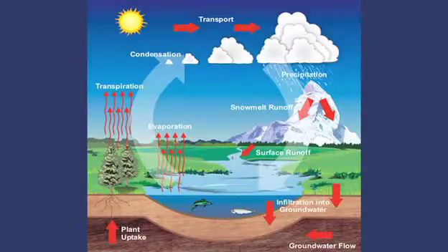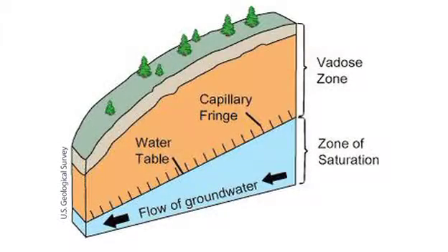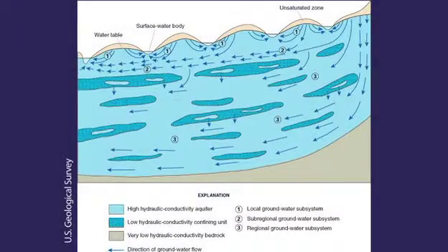Infiltration is the process by which precipitation is abstracted by seeping into the soil below the land surface. The infiltrated water moves predominantly in a vertical direction until it reaches the groundwater table. Groundwater flows laterally along a piezometric gradient towards zones of lower elevation and eventually goes on to constitute the base flow of streams and rivers.